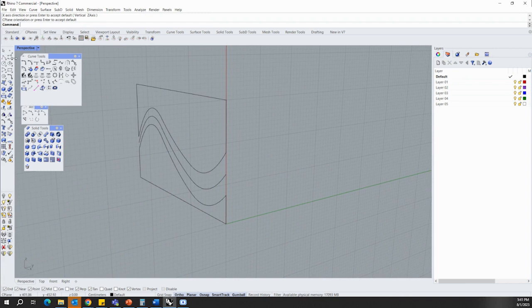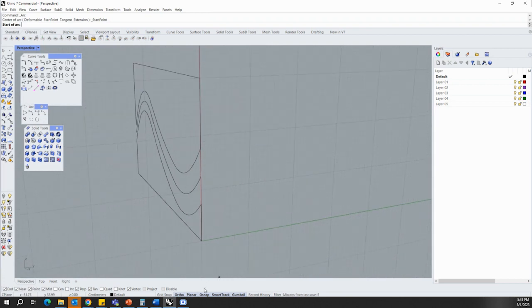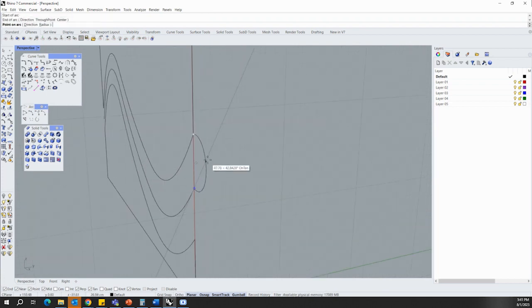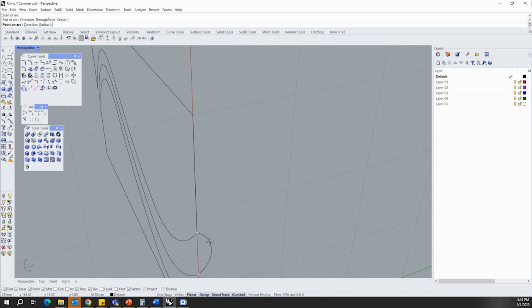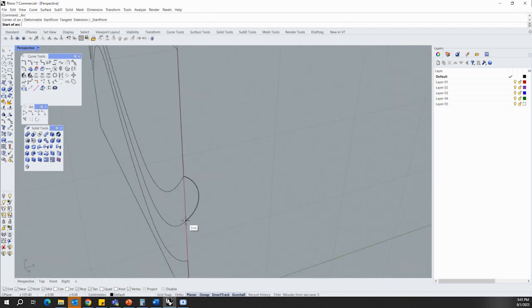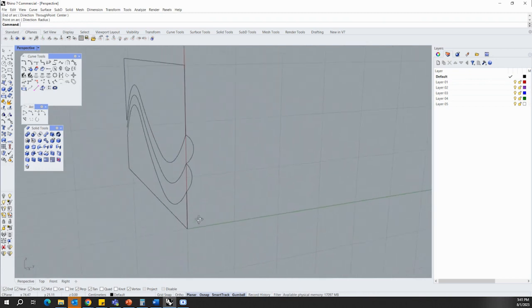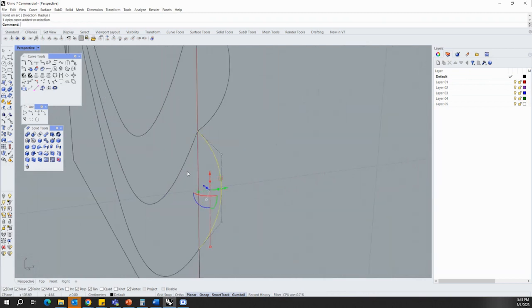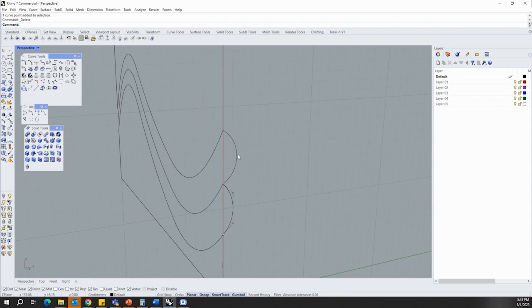Once after that, you can go to the arc tool and draw the arc, start point, end point arc. Click that. When I am drawing this, I can switch off this auto, otherwise it will be snapping to the 90-degree angle. So I'm switching off that, clicking here and here, and you can just draw an arc like this. One more time, click here and draw an arc like this. Once it is done, you can just click and delete the middle point of the arcs. It's not required.